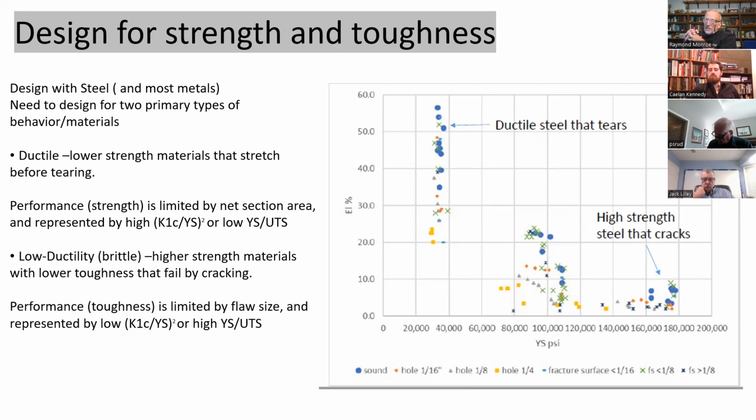And the yield strength can be affected by all kinds of other things, including the way I make the measurement or the surface finish. And I know, Paul, you'll want to come back and talk about that, but those are really fundamental, or alignment of the machine. So yield strength and ultimate strength are redundant. Elongation and reduction in area are redundant. So if one of those is correct, I'm pretty confident that the material has the properties I want.